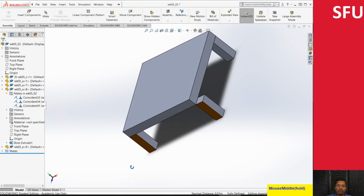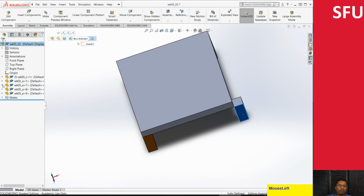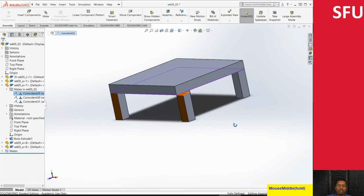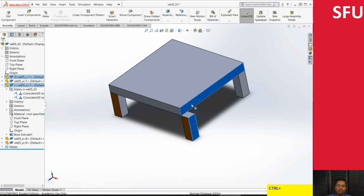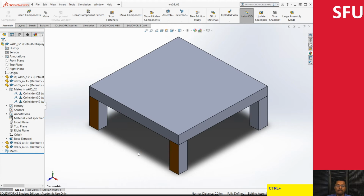We'll do the same thing for the fourth leg over here. I don't know which one it is, but I click on it, it gets highlighted. Drop down, double check, and we go to mates. Let's look at the problematic mate again. This one looks okay. This one looks okay. This one not so much, so we'll delete this. Then select this face with the other face and make it coincident, which basically completes my table leg. Let's do Control 7 and again save the part.